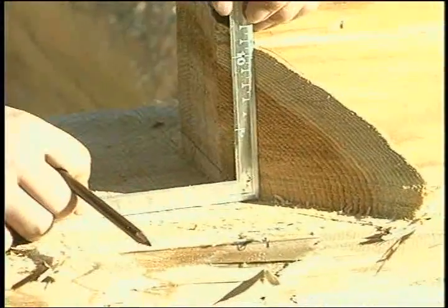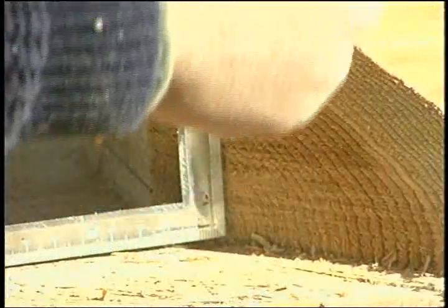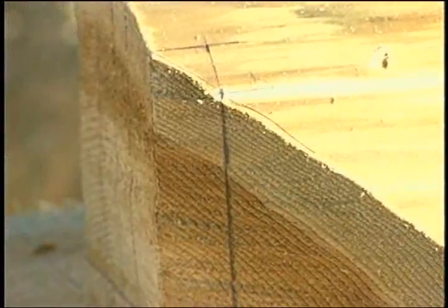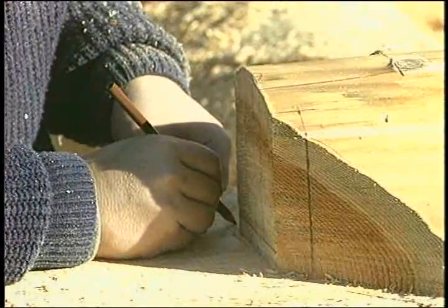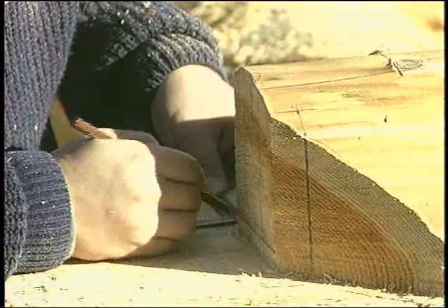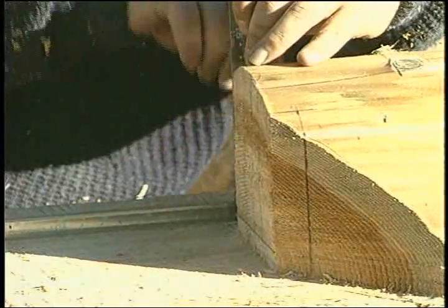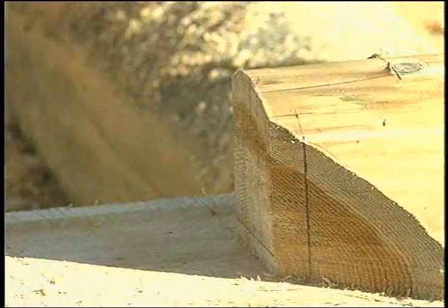Finish the 45-degree cuts, then mark in the back of the trim cut. Because the 45-degree cut may not be entirely plumb, make your line square with the top of the opening. This small cut might just as well be done with a sharp chisel.